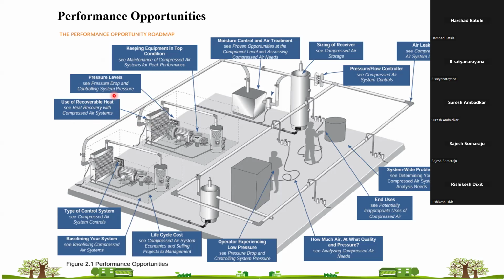During an energy audit, there are multiple energy saving opportunities. Like hot water can be generated through a compressor. But if there is no use of hot water in your entire plant, what is your use of hot water? Heat recovery from the compressor has to be continuous.